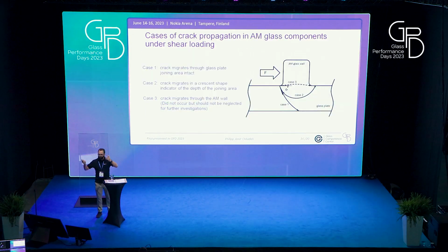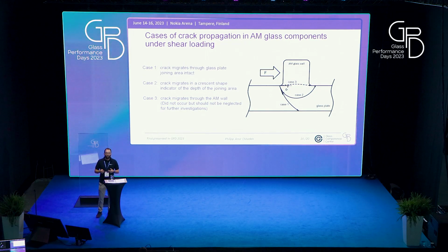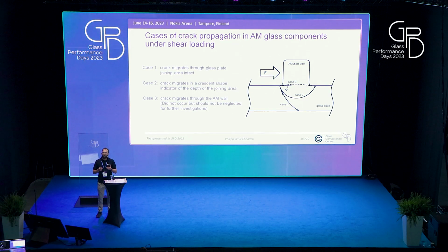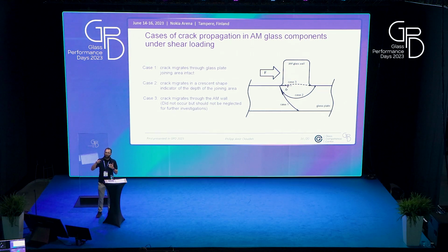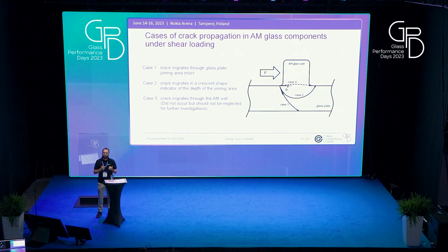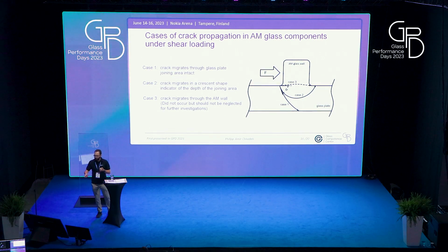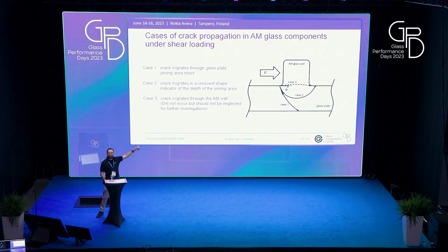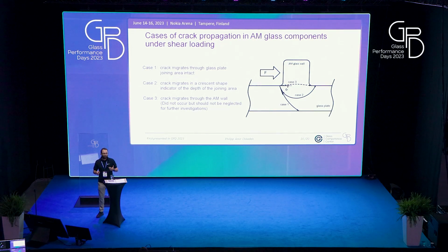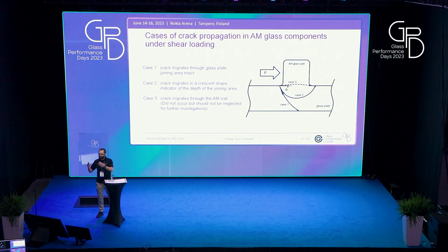We know from our studies that failure in glass happens where tension and surface defects overlap. And the question is, is this contact angle a surface defect? We know that the surface changes, so we have a small surface where a lot of force has to go through. So this also indicates the crack origin. And we know from other shear tests on other brittle materials that this opening angle of roughly 70 degrees is the same as the literature says.